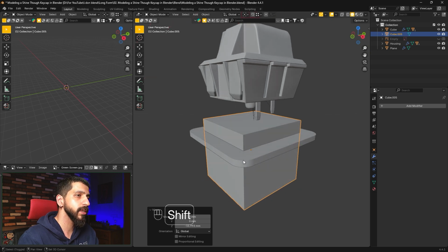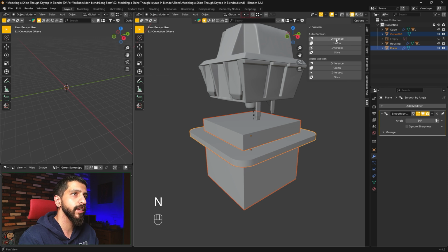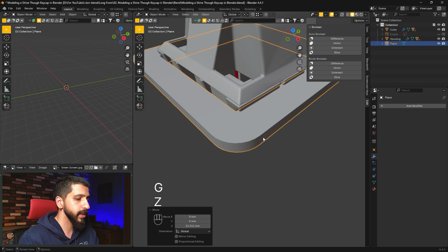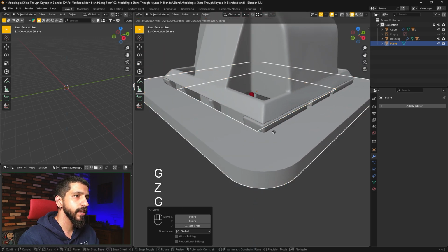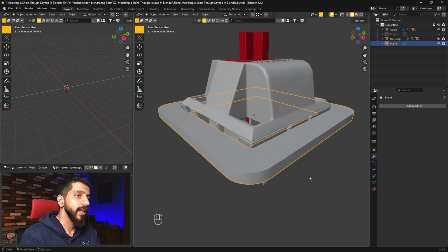With the cube selected, holding Shift, select the metal plate and Bool Tool add-on and hit difference. Let's bring our metal plate up and see how it looks. And I can say that I actually really like this. This looks pretty cute. And the last thing I need to do for our metal plate is beveling these sharp edges so it looks more natural.